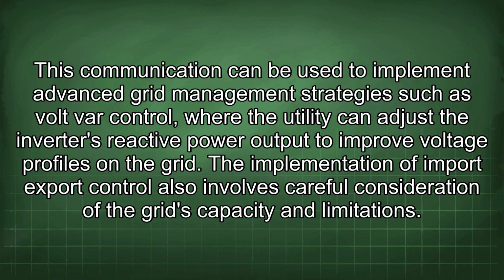This communication can be used to implement advanced grid management strategies such as volt-VAR control, where the utility can adjust the inverter's reactive power output to improve voltage profiles on the grid. The implementation of import-export control also involves careful consideration of the grid's capacity and limitations.